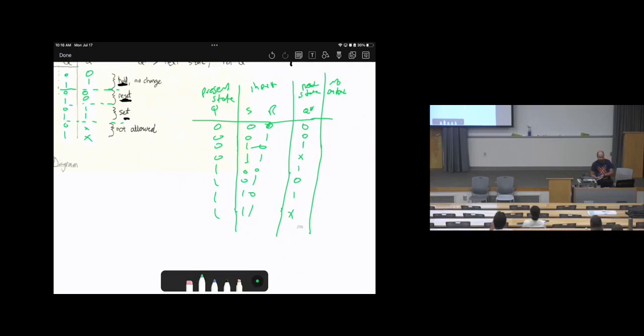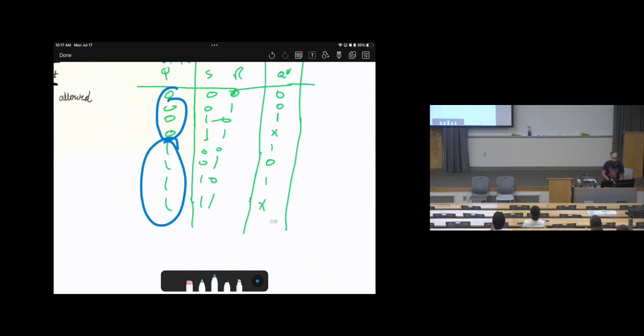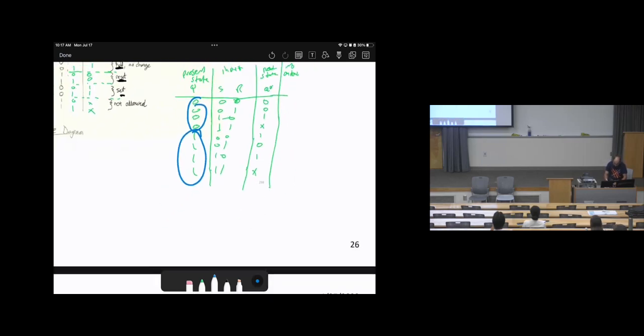You will see here there are no outputs. So there is no slash over something like 0 over 0, and we cannot say that it applies to the Mealy model or Moore model. There is nothing like that because there are no outputs. There is only a state table without any outputs. Look at the states. We have one option of zeros, the other option of ones, right? So we can do two circles, one circle at 0 and the other circle at 1, because we have only 0 or 1. We have only Q. It's not like in the first example where we had A and B.